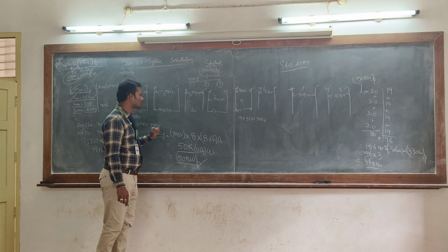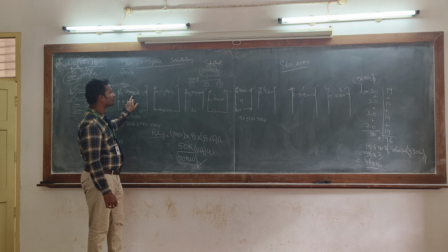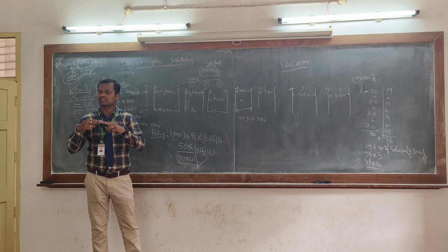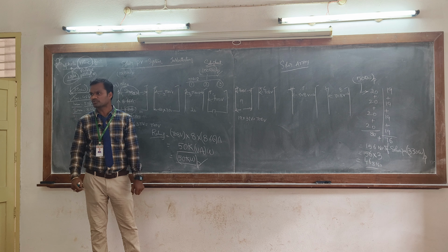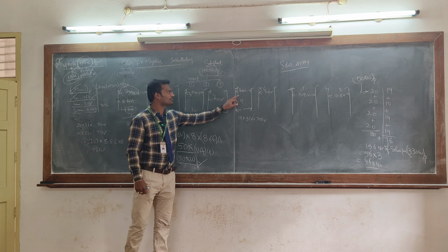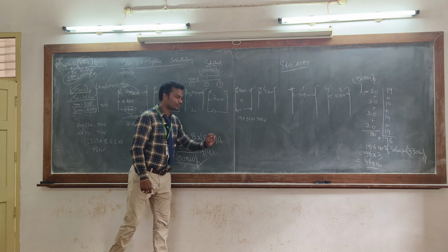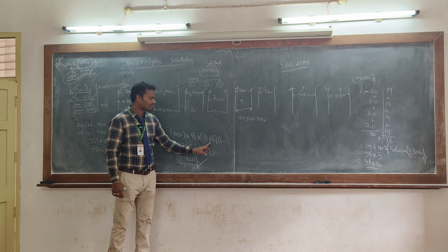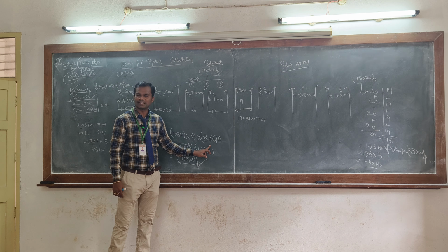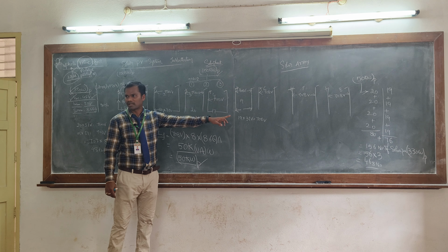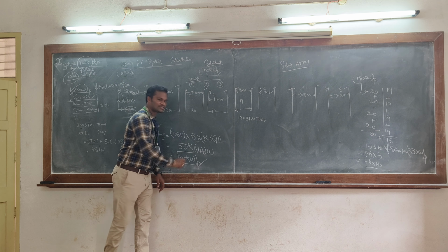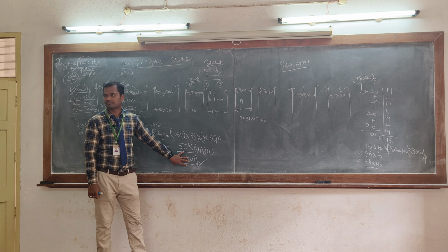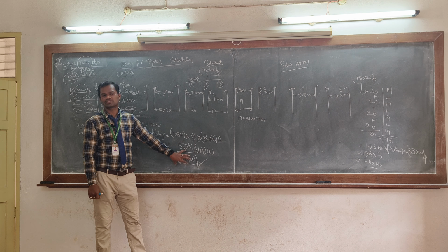If you group all of these, you get the parallel voltages as 740 and 708. But as per electrical engineering, if you have two parallel voltages, whichever voltage is lower, that voltage you have to consider, that will come into action. Therefore the resultant voltage is 708 volts. We are connecting the panels in series, and we have a total current of 8.88, and all these are once again connected in parallel, a total of 18 parallel. So resultantly the system develops 50 kilowatt peak. This is how we are generating.